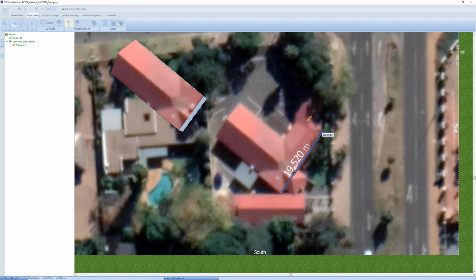It's up to here. Then we have to go to the corner upper left, and then we have to move down to this part. Again, please press the enter button, and now we have to draw the ridge of this building. Maybe it's to here. Okay, then to interrupt the drawing mode, press escape. We can adjust it a little bit. It's here, more or less a rectangle.